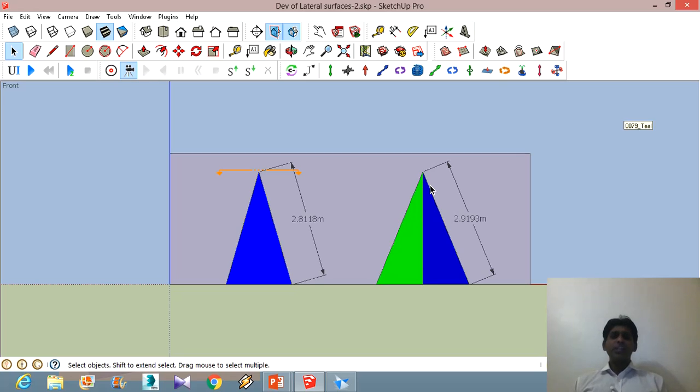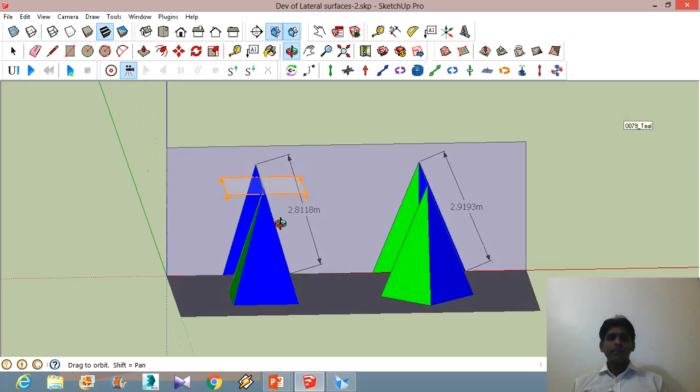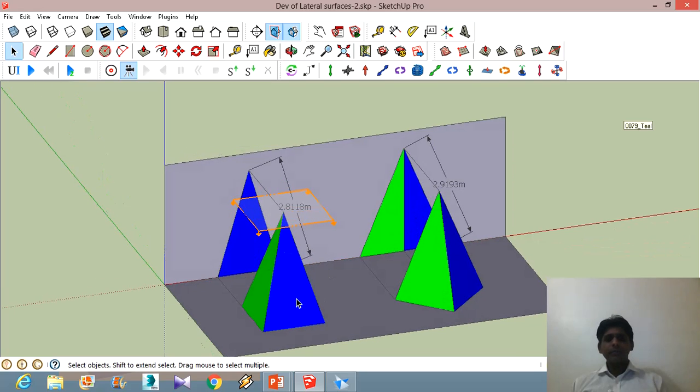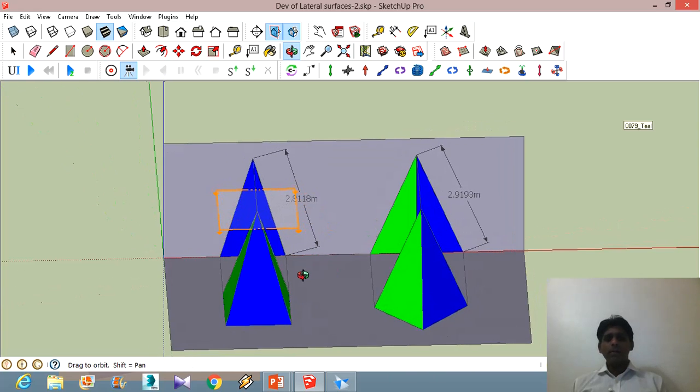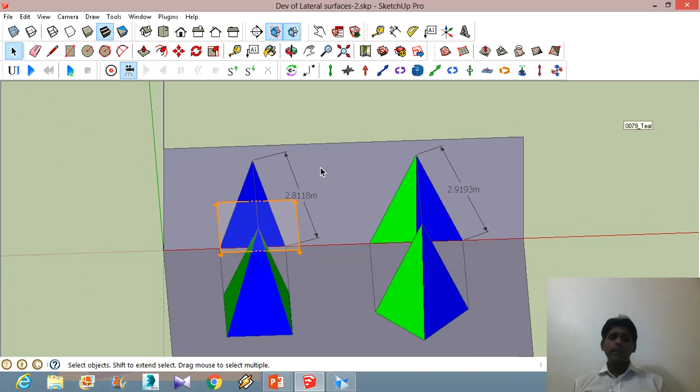Now, as mentioned earlier, in development of surfaces, everything has to be done on the true length. So obtaining true length is very important. I will explain this statement. In this particular position, you will see that none of the slant edges are parallel to the vertical plane.